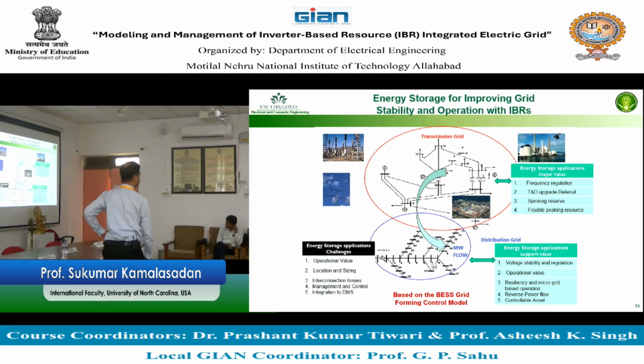These are some of the things which you have not discussed, but you will, interconnection related aspects, voltage balancing, these things. Oh, by the way, if you are going to get the reactive power from the inverter, you cannot get the reactive power from the inverter without some active power source. This is something which, for some people, is kind of unknown. You may think that reactive power is free from the inverter. No, you need some active power because of the losses and other things.